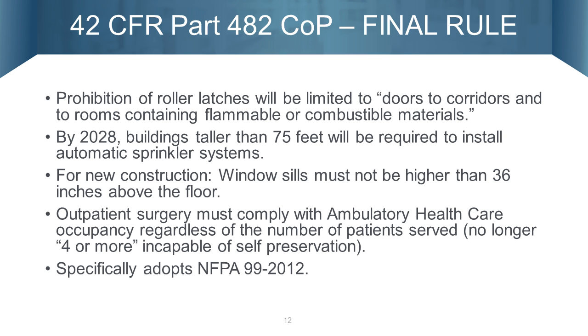The other thing that high-rise buildings must comply with by 2028 is to be fully sprinkled. Many states have required facilities to be fully sprinkled already, but there still are quite a few out there that are not fully sprinkled. Under new construction, window sill heights 36 inches above the floor.